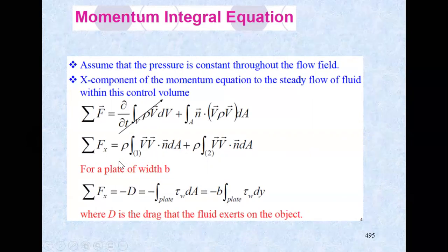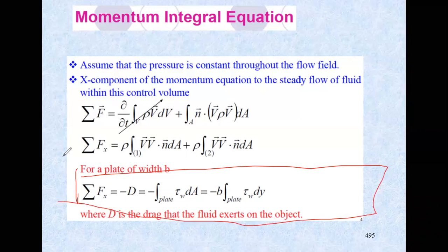Then for a flat plate with known width b, the drag force is equal to the integration of tau w dA, or you can take out the b value, so it only depends on y. Tau w dy will be your drag force, that the fluid exerts on the object.